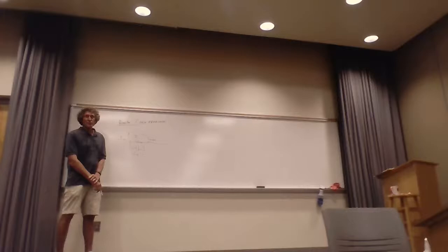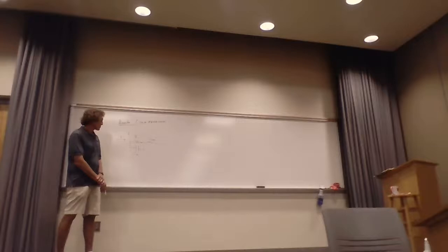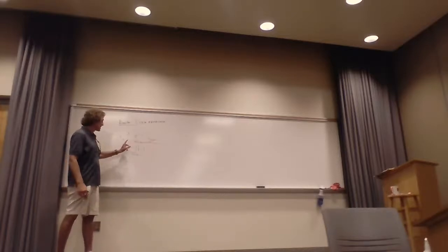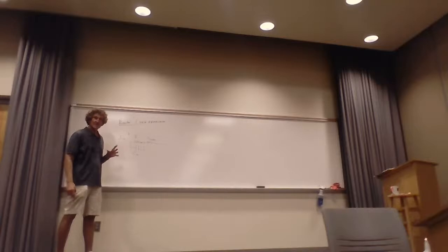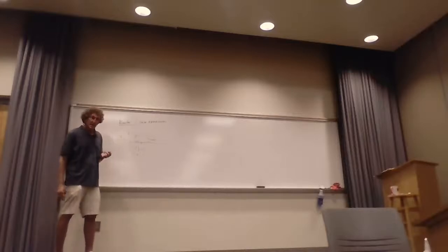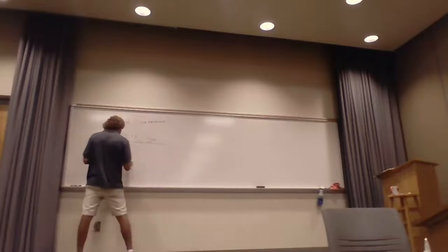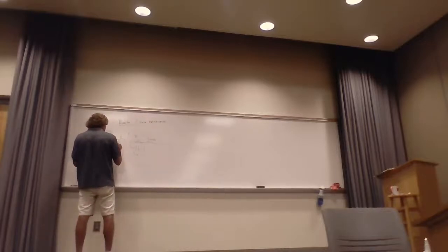I want to make mention of one other thing. This is just a first order shot at modeling it because, quite frankly, this capacitance could just as well be put across the lead inductance at this point. All right? This is an approximation that works a lot of times. This is basically something that works for carbon resistors. All right, so if we know that, the next thing we want to do is see what this impedance looks like right here between these two.